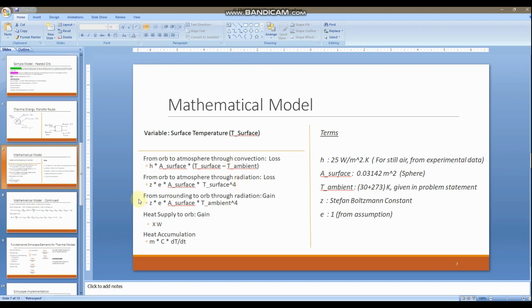Right. So once again, in the real case, the emissivity depends on the nature of the surface and the nature of the coating that's applied on the surface. And it's kind of like H, where you can either model everything down to the last detail and evaluate an actual emissivity, or you can do some experimentation and figure out the average emissivity, or you could roll with an assumption like the one I had given over here.